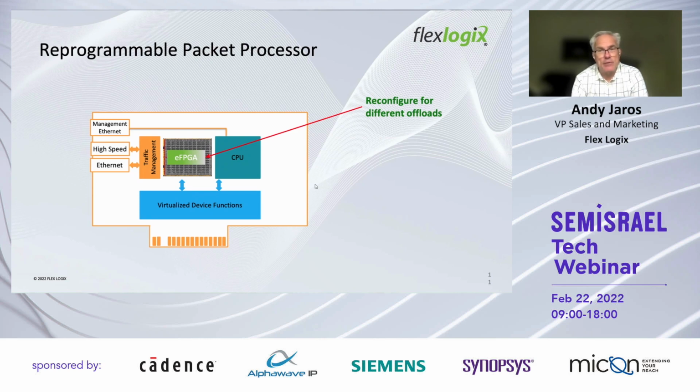There are several ways to address the programmability. One is to use embedded processors. However, they inherently induce latency due to the dependencies on local cache memory, with direct impacts to throughput. You can use dedicated state machines like we talked about earlier. They give better performance, but are inflexible once committed to silicon. An embedded FPGA is an ideal solution because it provides near ASIC performance, yet has full reprogrammability. An added bonus is that the designers do not need to over-design their state machine to anticipate every possible future use case. They simply program in a new state machine.